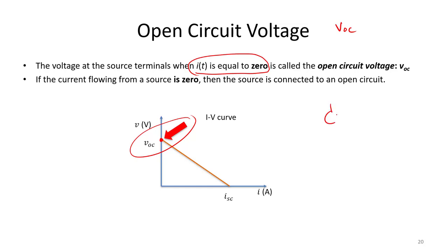So basically, it's similar to having a circuit where, notice if we had a 5-volt source and a 10-ohm resistor, here the open circuit voltage would be 5 volts because there's no current across the 10-ohm resistor. It's open, so we're basically sitting at a 5-volt potential difference. So once again, open circuit voltage is the voltage we would see if there's no current flowing through our circuit.